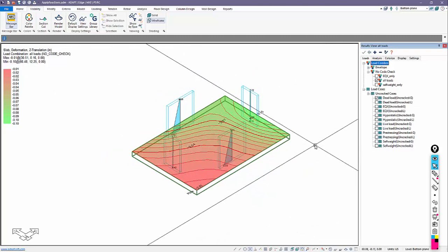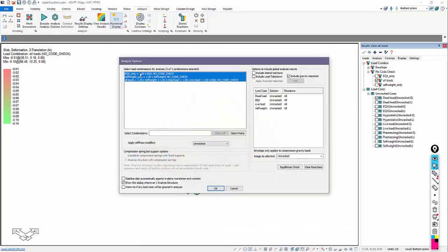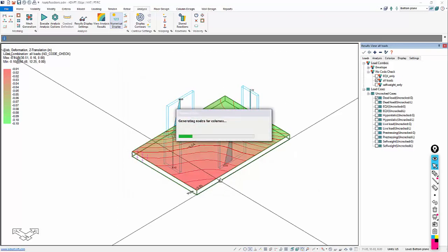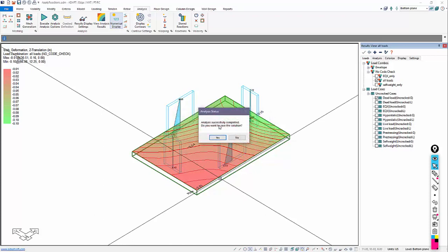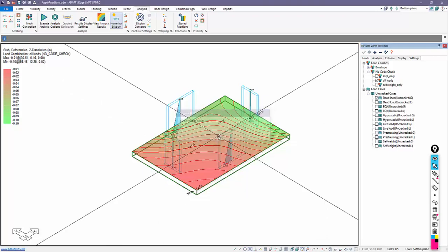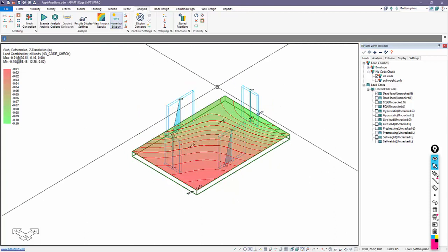Now if I rerun the single level without the EQX only load case, then we're not going to get the stability warning. We can still reapply reactions, but we don't have this isolated EQX load combination that triggers that stability warning. This will run and just give us a solution that says, hey, this solution is reasonable. There's no excessive displacement in this particular run because we excluded that one load combination. This allows us to obtain that solution once we rerun that.